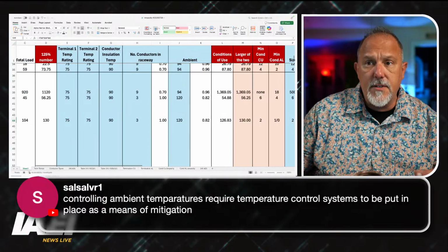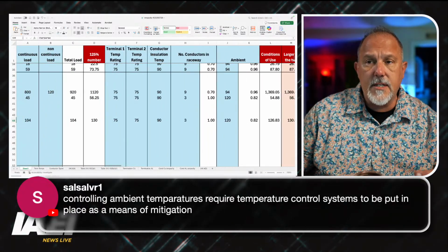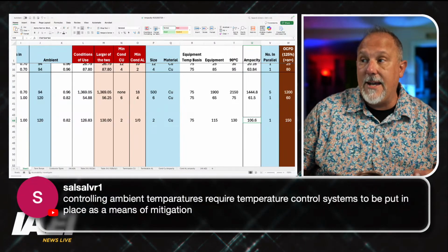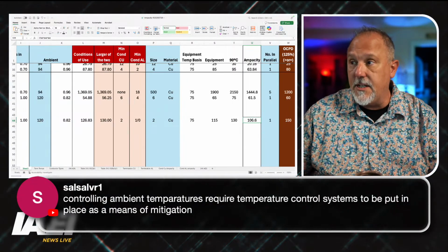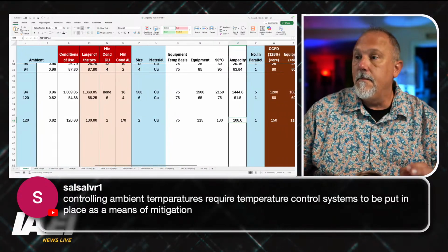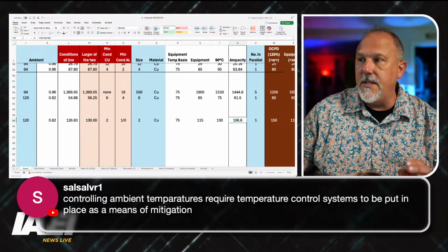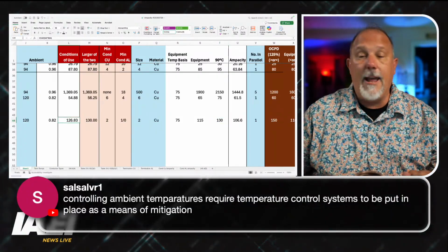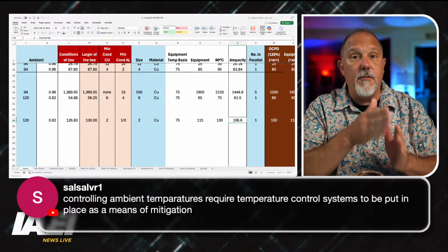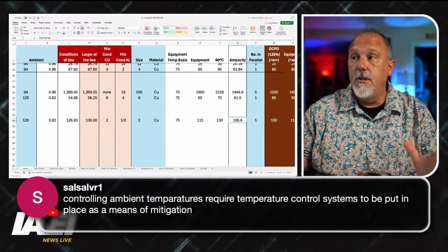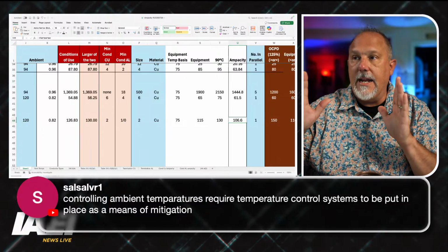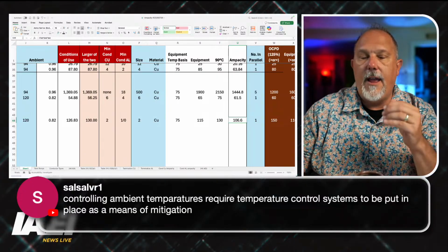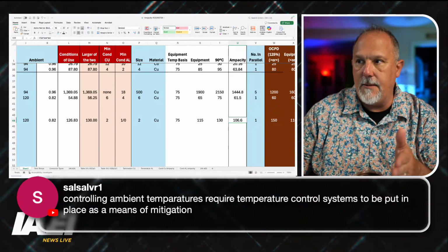106.6, and I have what? 106.6, 104. That's not going to work because, yeah, it would work, because that's the ampacity of that conductor based upon the conditions of use. So I'm good to go. Because my 90 degree C column has to be greater than the 126.6. Not my overall ampacity; it has to be greater than the load, right? So I go to a number 2 based upon those conditions of use, and that gets me to 106.6 amps.